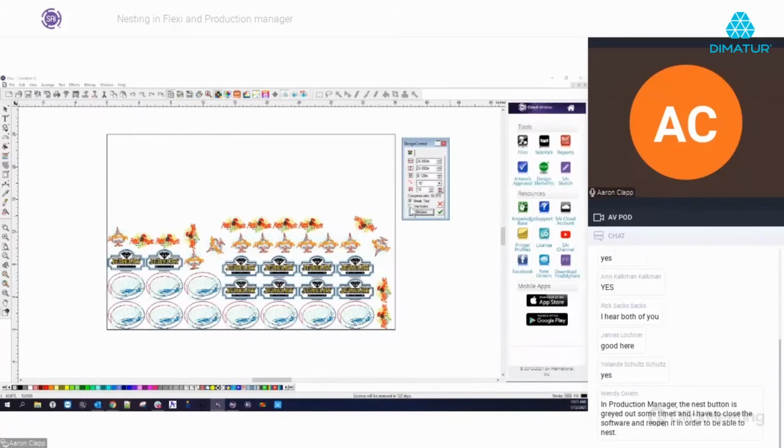Use holes. This is if you're going to be using some kind of a large cutout. Let's say you're cutting out letters of different sizes. If it can fit a piece or a letter into the hole of, let's say, an O, or inside the hole of a B or an R, then it will try and fit those in there. If you uncheck this, then it just won't try and nest anything in there altogether. This is if you're really trying to get as much yield as possible.